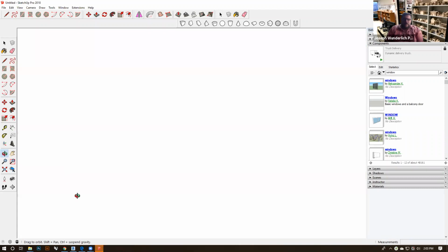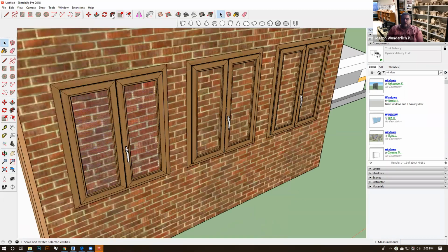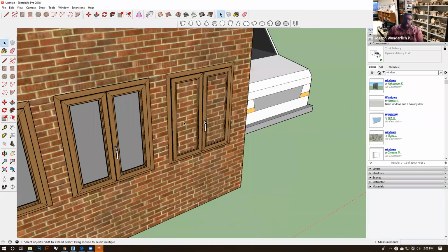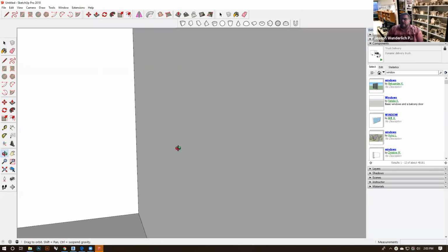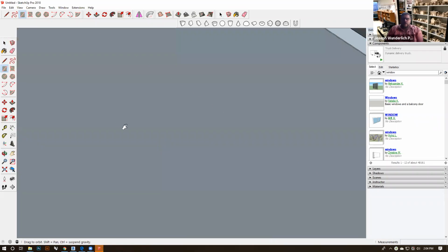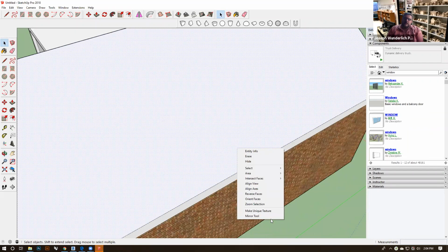There's all kinds of things. There are separate inspections for electrical, plumbing, structural, soil mechanics and runoff, as well as the fire code. In California, you have to go to the fire commissioner, I forget the guy's name, and you need special approval for that. You need special ADA approvals through other people in big cities, especially in California.